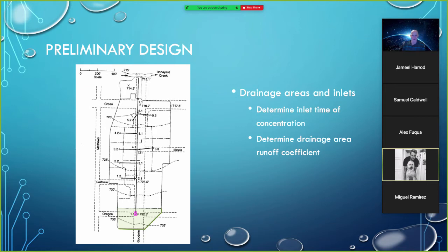And we would determine a runoff coefficient by looking up an appropriate value in a table of runoff coefficients, weighted by what other information we have on the project site, which we don't have in this example. So I know this is in Urbana, Illinois. I know it's a city, but what I don't know is how many trees versus houses there are. So I would need that additional information to come up with a reasonable runoff coefficient.